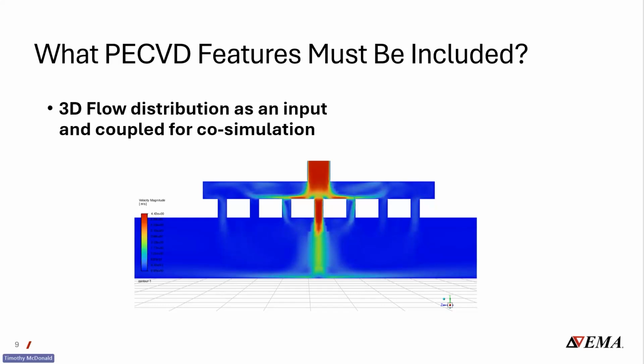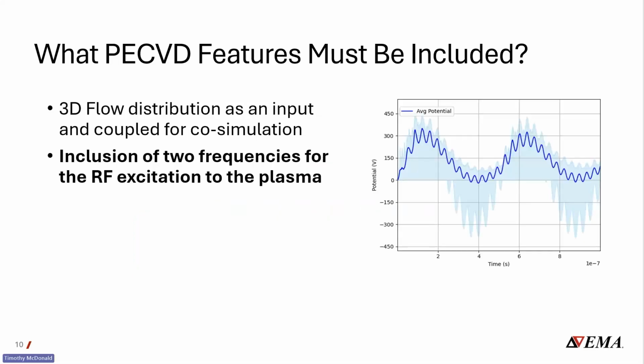That's why we say at EMA that three-dimensional modeling is not just a nice-to-have feature, but it's essential. We need 3D for the chamber, the wafer, the plasma. They're all inherently three-dimensional. And because the industry has been using 2D or simplified models, they're often missing these critical asymmetries. So that's the reason we put so much time and bear the computational expense of going for full 3D.